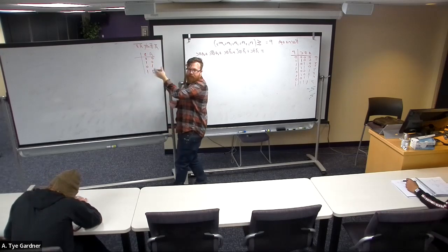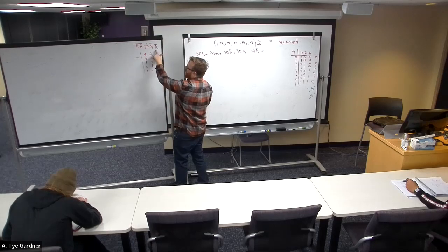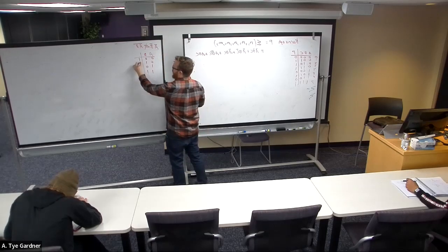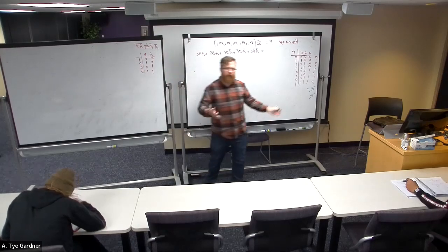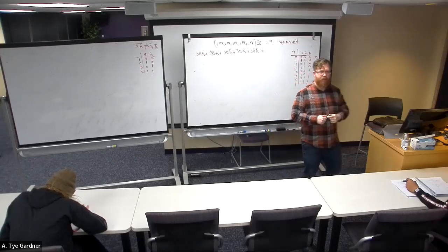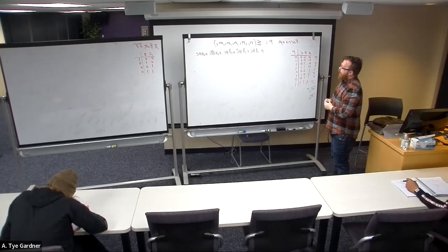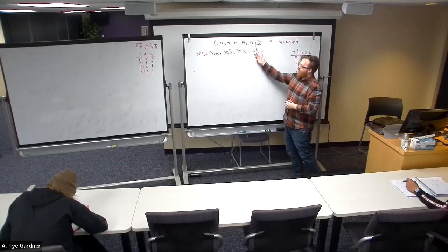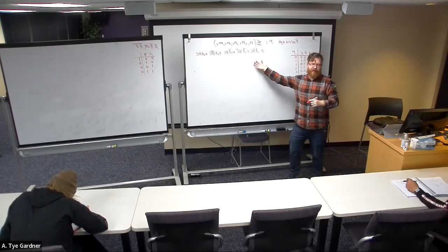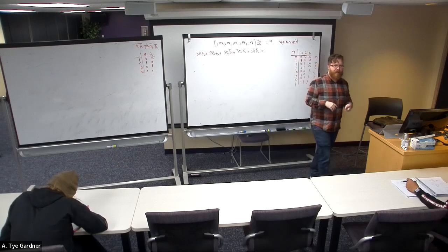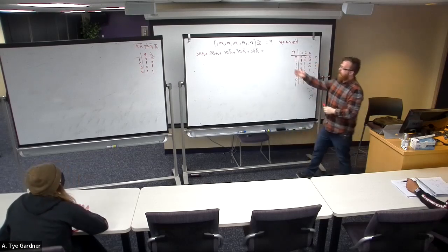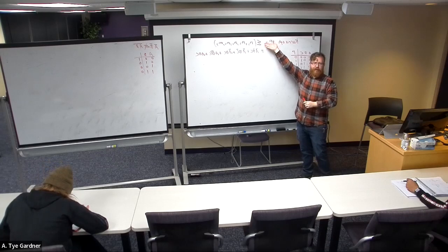Our truth tables, right? We can just go figure it out. Where is not A and not B? Here's a 1. There you go. What is it? It's a NOR. So that would be a NOR gate ANDed with C, but we'd rather use a 3-input AND gate, really, because that's what a min term is. This is a canonical form, meaning everybody will understand what you've written if you write it in this form.